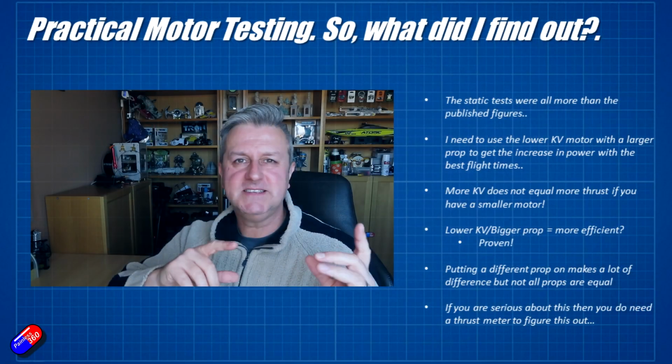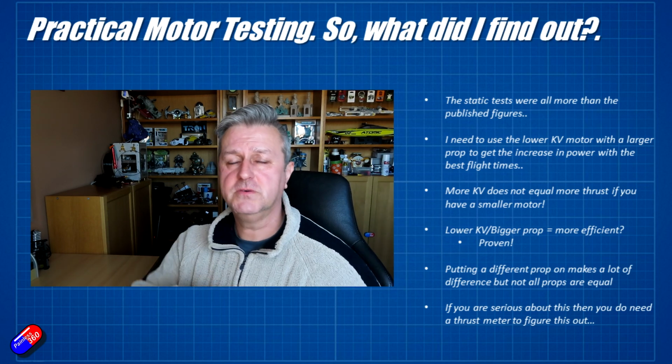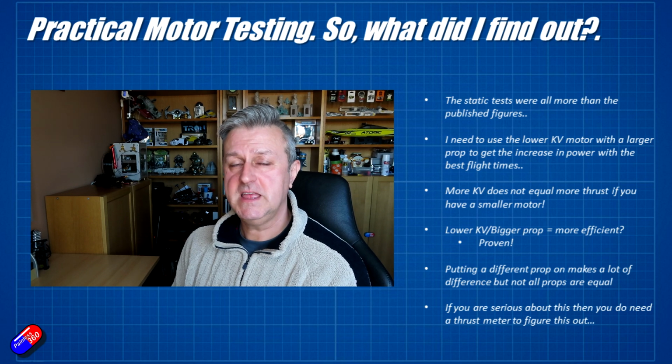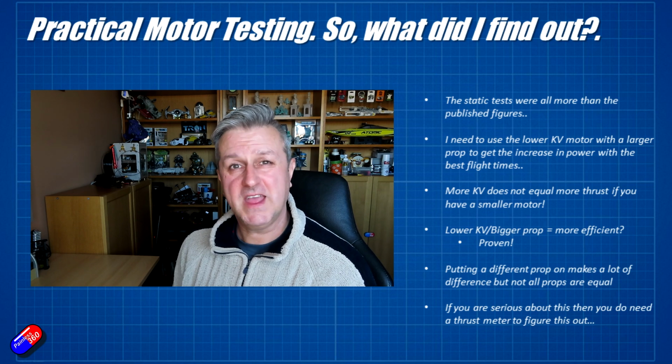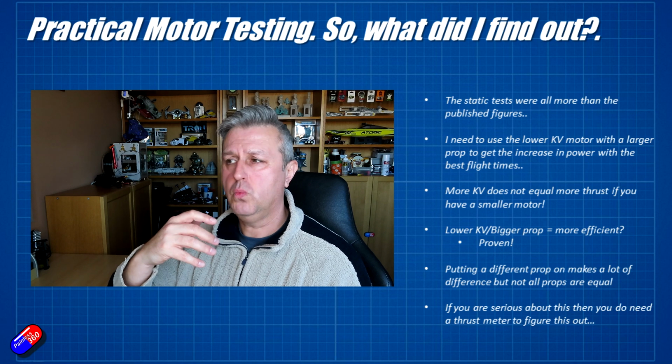The static tests for all of the thrust that we played with for the motor and prop combos were significantly more than the stuff in the T-Motor tables. So for the stuff in the T-Motor tables, you can be pretty confident that you're going to get it in a real world example, particularly a static thrust test.